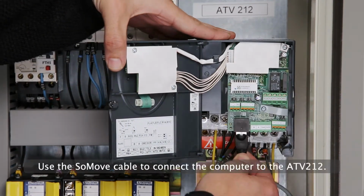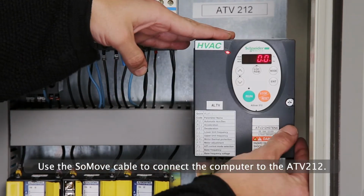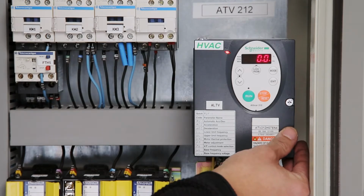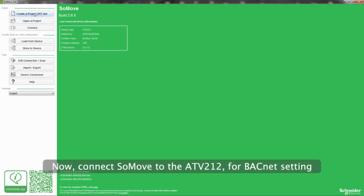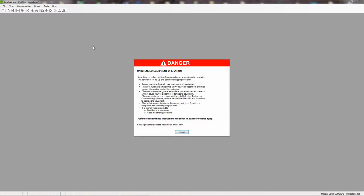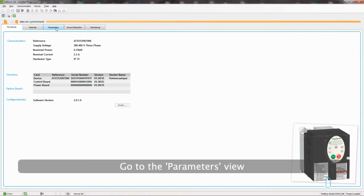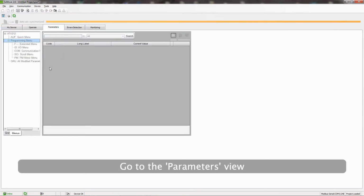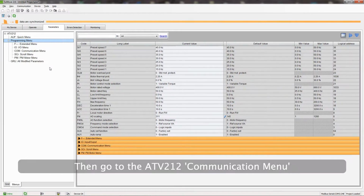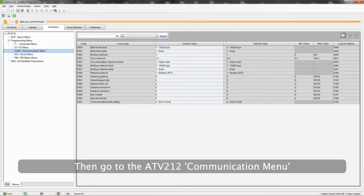Use the SoMove cable to connect the computer to the ATV212. Now, connect SoMove to the ATV212 for BacNet setting. Go to the Parameters view. Then go to the ATV212 Communication menu.